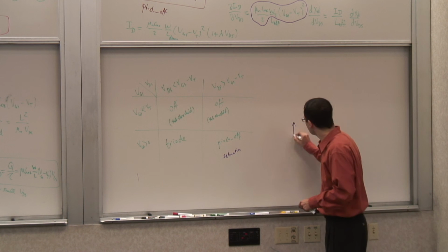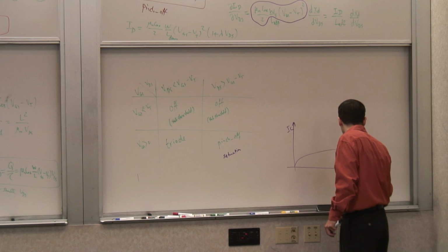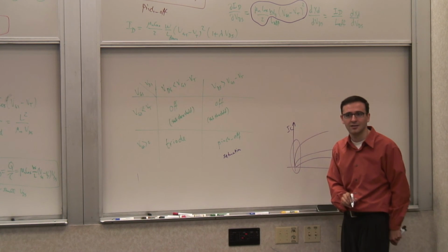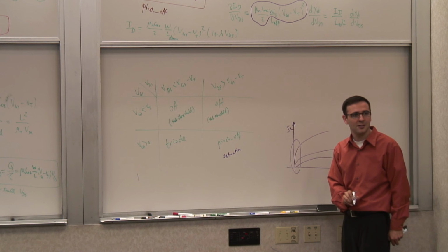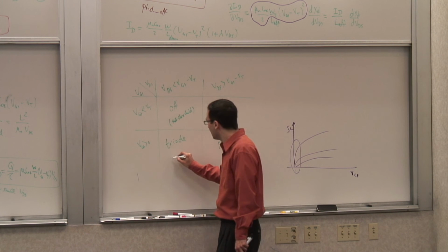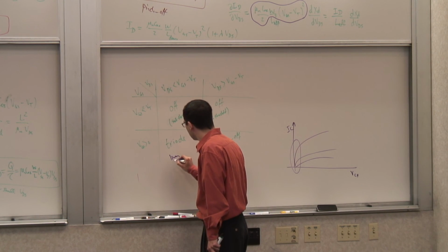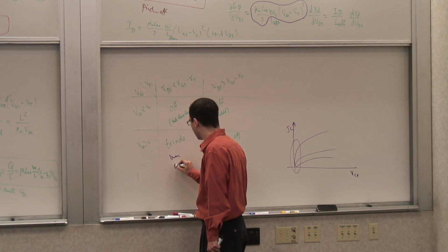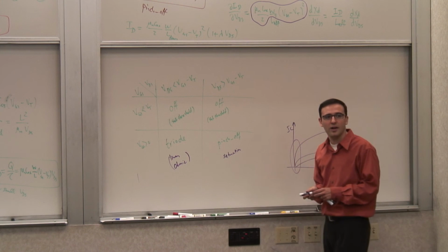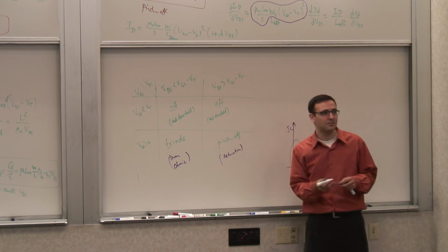Do you remember the bipolar IC versus VCE curves? This was the saturation region. But now this corresponds to the triode, which is also called linear, where it's not exactly linear, and also ohmic, where it's not exactly ohmic.